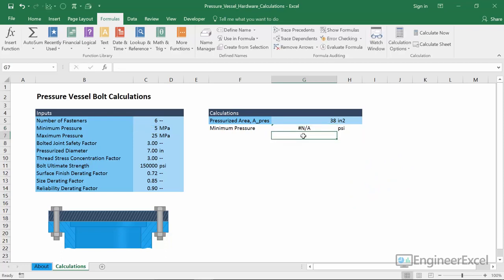And the tricky thing there is that it actually did an autocorrect on MPA right here. It only capitalized the first letter, and it really needs to be both letters capitalized. So when I correct that and hit enter, it does the unit conversion appropriately.